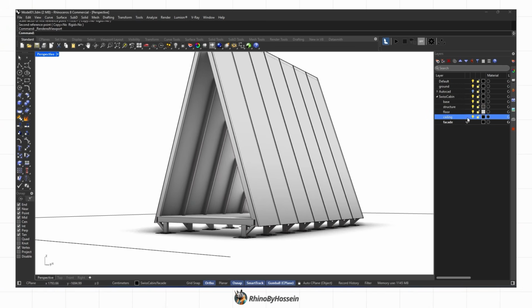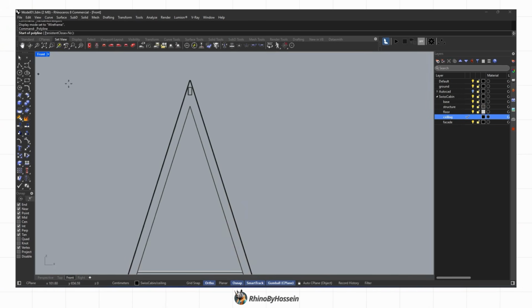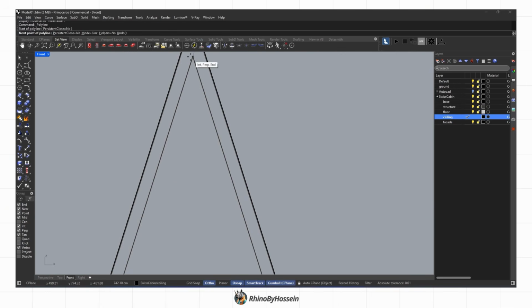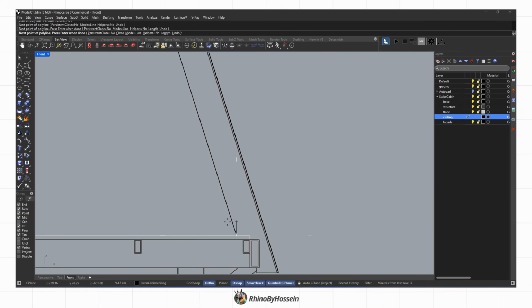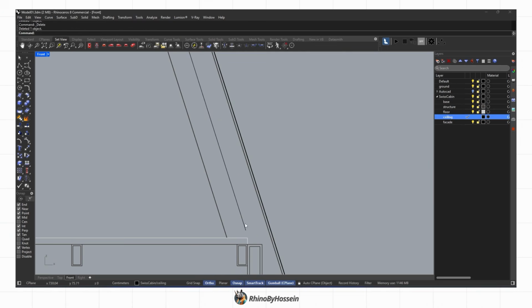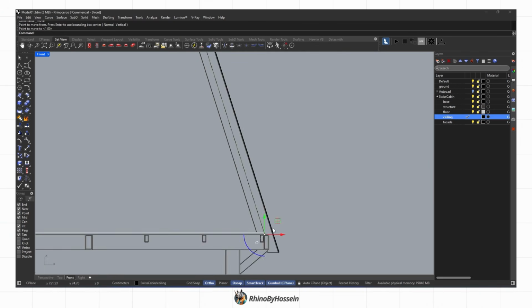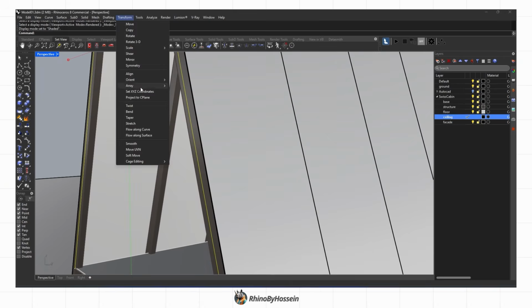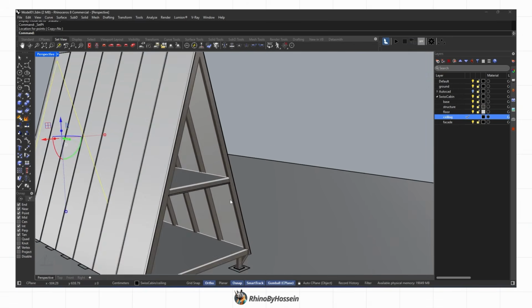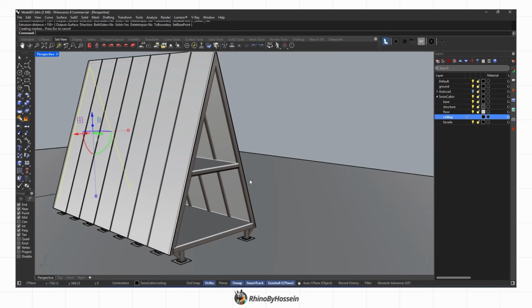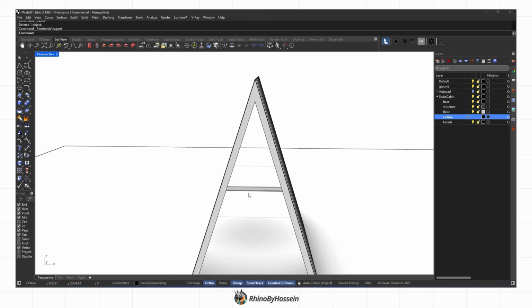The first step is to select the ceiling layer and, as shown in the image, draw a polyline. To ensure the interior wall is slightly away from the beams and gives the model a cleaner look, we offset it by the desired distance using the offset command. After adjusting the distance, I extrude this line to the full length of the structure, so the interior wall is fully formed and integrated into the interior space.